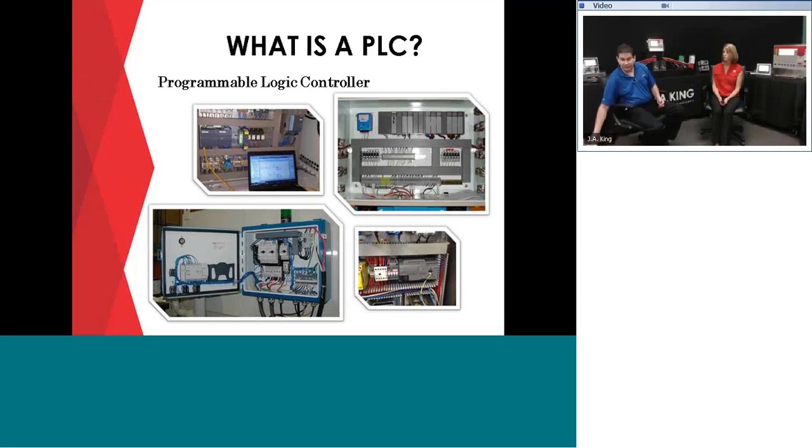Each one has to have some type of display for human interaction with it, whether it's operator or data collection or whatever. So you're going to have an HMI connected to it that's programmed. Here's the Siemens one, same type of thing. You've got a controller, different I/O, and different communication modules. You find these in almost all manufacturing equipment, process control and all that. They're really freely programmable, and you can do a lot of things with them. Typical brands? Siemens, Allen Bradley, Omron. There are 50 or so more manufacturers of them. There's quite a few.